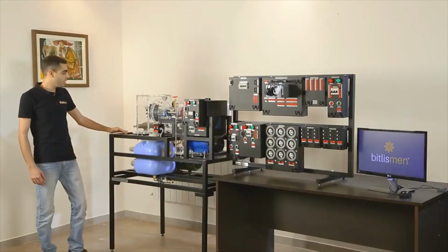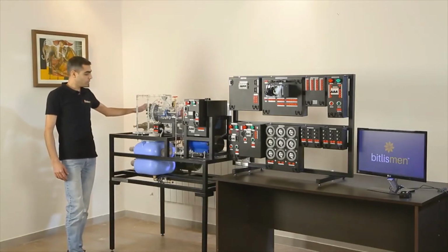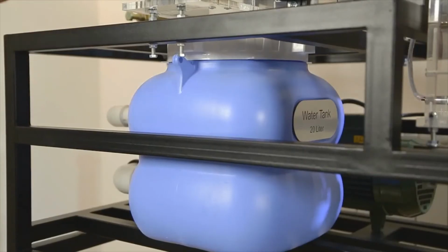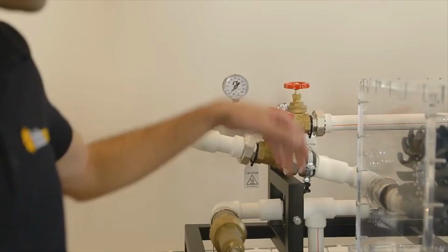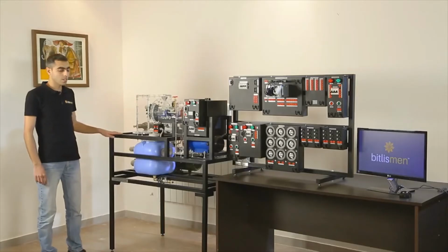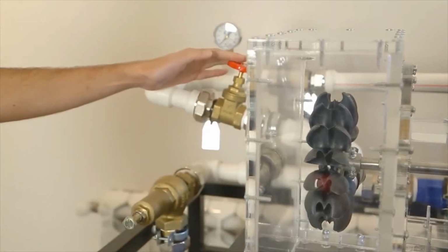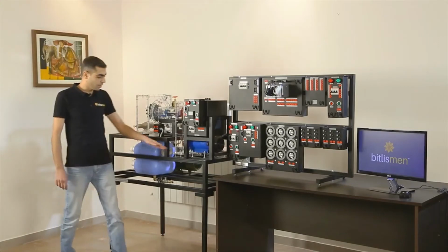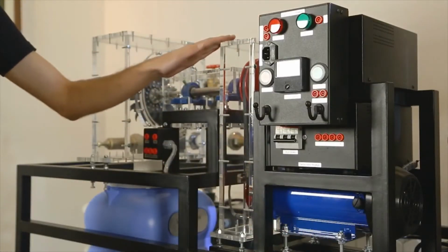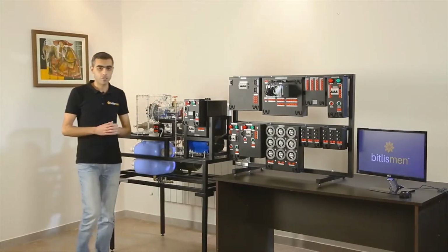The first part is the infrastructure for emulating the head of hydropower station, water pressure and flow. It consists of water tank, pump, and the pipeline with valves and sensors. The second part is the hydropower turbine with its governor, which is the valve. The third part is the generator with the excitation control and the V-belt drive for 50 and 60 Hz options. Now let's pass to the demonstration of some functions of the trainer.